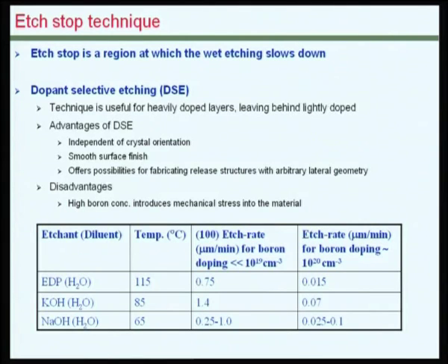In doping, what we do is we introduce impurities and in a controlled fashion drive these in to the required depth, and hence there could be a significant variation in the etch rates based on the doping concentration.